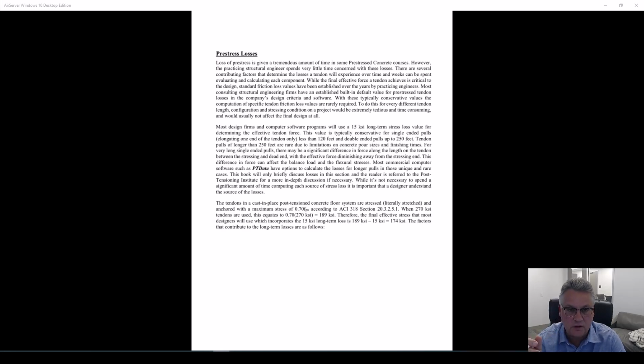Now, what is a pre-stress loss? Basically, if you stress one end of a long beam, and you only stress that one end, 200 or 240 feet away, the stress that you stress to on the left side won't necessarily be the stress that you get on the right side. There is some loss. And then to compound that over time, a series of factors build up that create a decrease in the amount of tension that you first put in the strands. So, where do those losses come from?